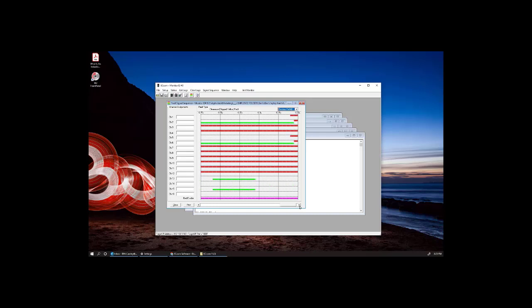Now, if you noticed right here, something happened where we went from a green directly to a red, which is bad, also known as a skipped yellow. The only thing that really can cause this is the controller, which is the one that takes the load switches and tells it to go all red. So in this case, the controller told the load switches that it wants to restart the intersection, so it skipped the yellow and went right to red.